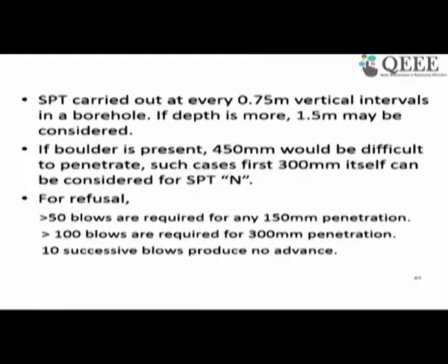So how many tests you do in a particular borehole, or how many SPT tests you carry out, depends on the total depth. If you have a total borehole depth of maybe 30 meters, you can test every 1.5 meters, or you can go by 0.75 meters if your depth of boring is just 10 meters. So it varies. The number also depends on the type of strata or their variability.